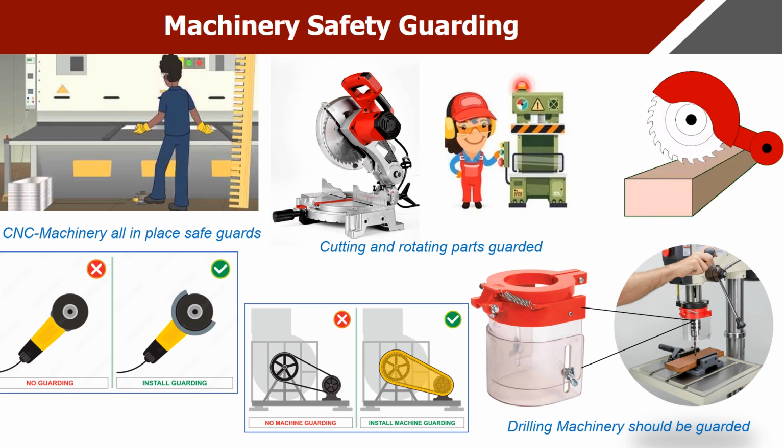7. Avoid loose clothing, jewelry, or accessories. 8. Use correct tools and attachments for the job. 9. Isolate power and apply lockout tagout (LOTO) before maintenance. 10. Report any unsafe condition or defect to supervisor immediately.